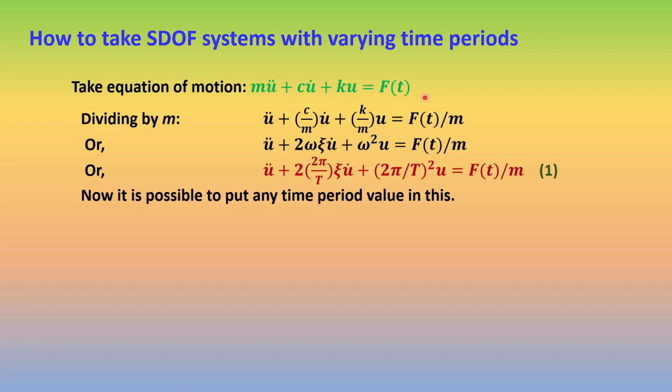And in our modified time history analysis equation and modified dynamic equation, we have incorporated the time period in the parameters, so that we can simply vary the time periods and carry out the time history analysis for each time period and get our peak responses.